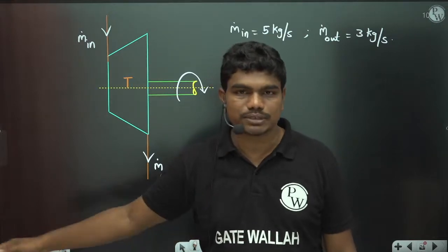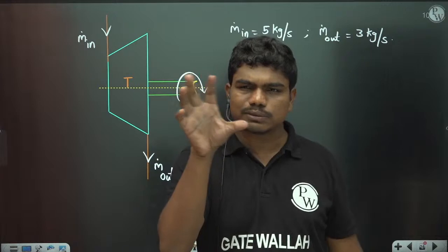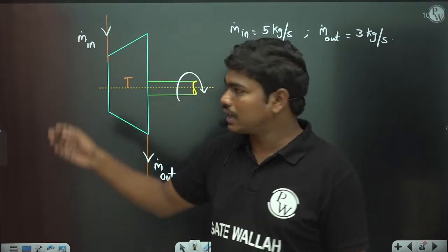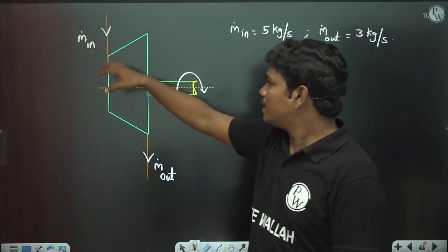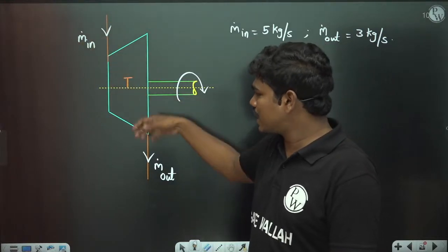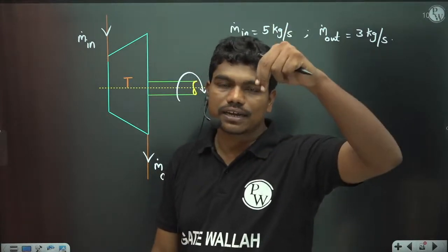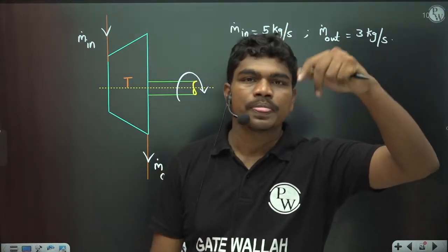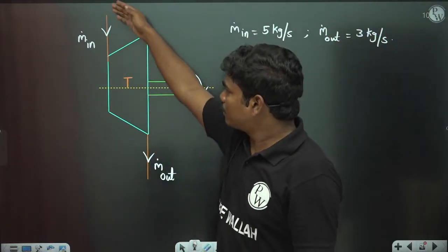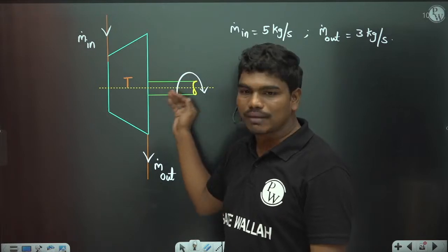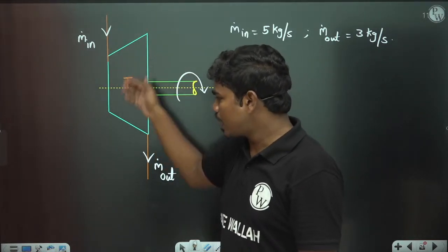Let us suppose if a shutdown has to be taken, then what happens? We will stop the turbine. So during that small stopping time, initially the mass will decrease and it will stop finally. Up till then, whatever mass is there inside will come out actually. Okay, only in that small time interval the mass inlet will be less as compared to the mass outlet. And similarly at the starting point, when there is no mass initially, the mass inlet will be more as compared to the mass outlet, because some time is required to fill the turbine with some volume and then it flows out.